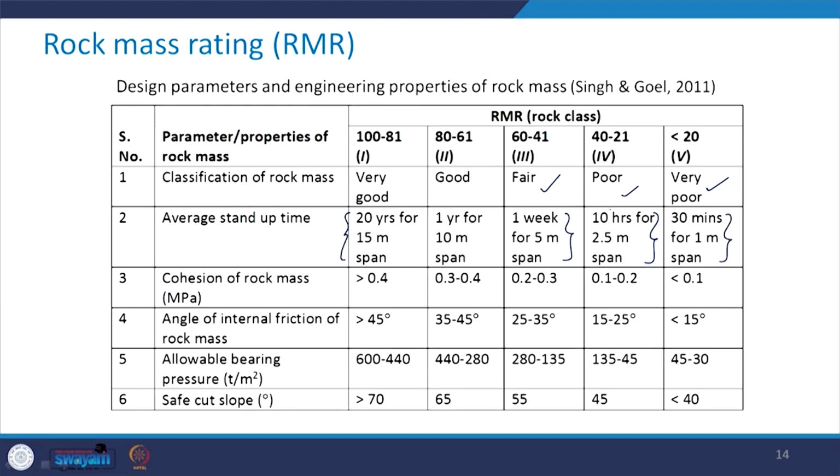So, although here you have 10 hours for this 2.5 meter span, you should not wait till 9 hours and then only go for the installation of the support system, because in those 9 hours the rock mass quality after excavation will deteriorate, and ultimately the effective average stand up time may not be this 10 hours for 2.5 meter span. So, we have to be careful about this.